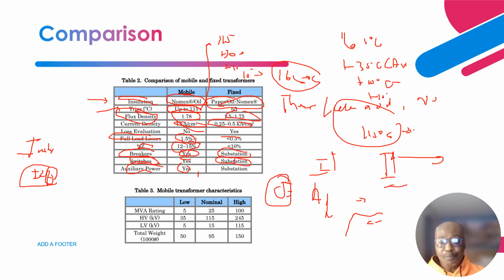You see it as basically you have the air insulated disconnect switches before the transformer, right? And usually this one has to be operated in a de-energized configuration. And auxiliary power, you see that substation power, right? Okay, so you see there's, let's say, 13.8 kV, 240 volts, or 120 volts, right? Okay, so now let's talk about the nameplate characteristics.